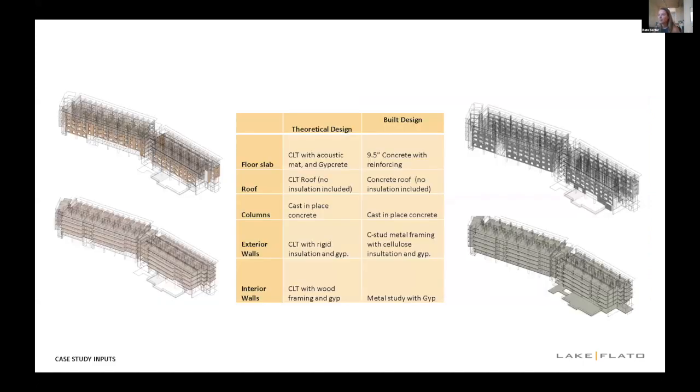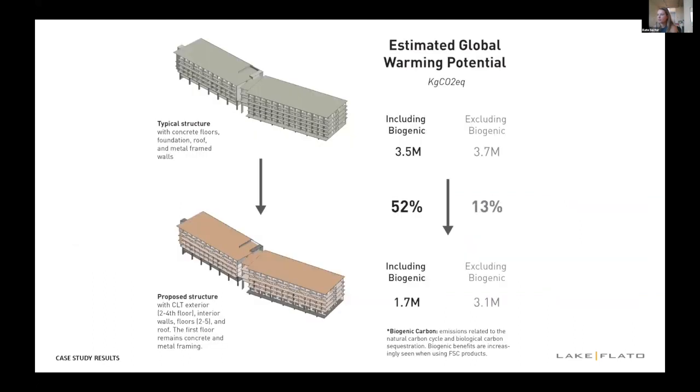Okay, so getting back to our design after doing all this research into it, we came down to essentially doing a very similar process in Tally where we copied our model and ran a different scenario on it using different materials. So we decided to go through this design using primarily CLT. And so we wanted to compare if you had your traditional building of concrete and steel, how would that compare to using CLT instead? And this is just within the structure.